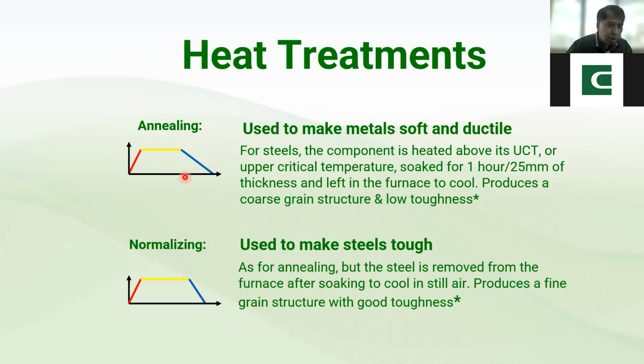So this one, ito hanggang dito. So mas matagal ang cooling down ng annealing compared sa normalizing, mas maikli. Okay? Kung nag-Boswell heat treatment ka, siguro ang mga cooling down mo rito 200 degrees centigrade. While on this one, pagkatapos mo mag-soaking, patayin mo na yung makina, huwag mo alisin yung insulation, cool in still air.